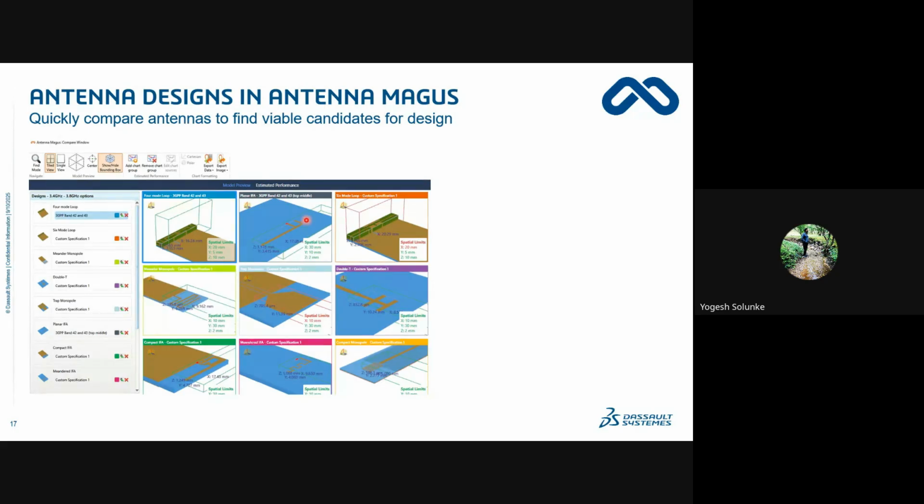Like we have seen for mobile phone, the requirement is an inverted F antenna. So that can be very easily exported from here. If you want to bring any CPW-fed antenna, you can see there are some listed here. And away from that, there is a big library of antenna makers. Once you use CST, depending on your requirement, you can set up antennas also here.